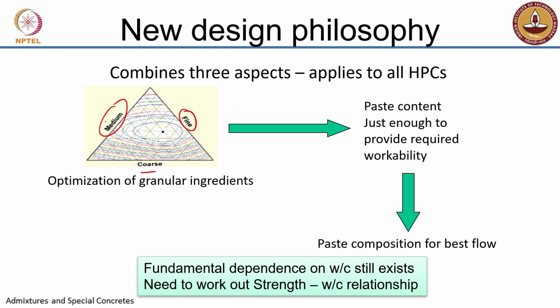Right? But all this has to be done with a caveat because you can't obviously choose material combinations that have too much in excess of one type of aggregate over the other. For instance, in concrete, you'll not choose a mixture which has only 10% fine aggregate. Right? That's not a decision that you'll make. You'll not choose a mixture that has only 20% fine aggregate. You'll choose a mixture that has significant amount of fine aggregate to avoid any problems of segregations that may happen in the concrete. Right? So your choices with respect to the material combinations are not going to be infinite when you do this experimental evaluation of the mix that gives you the lowest voids content.